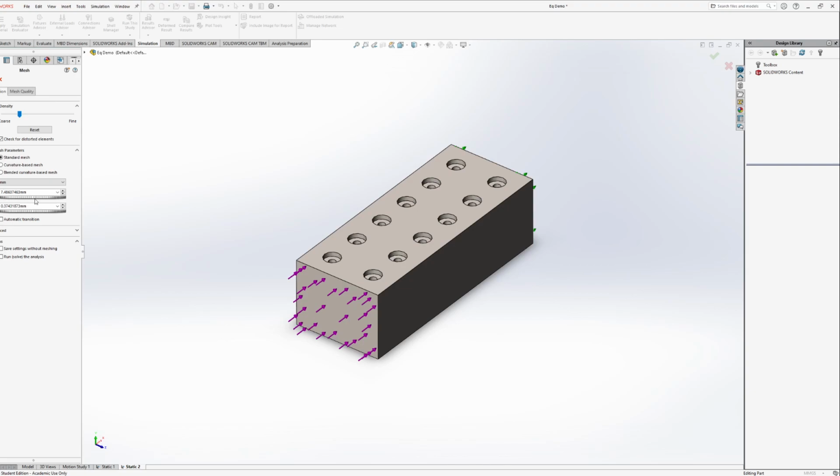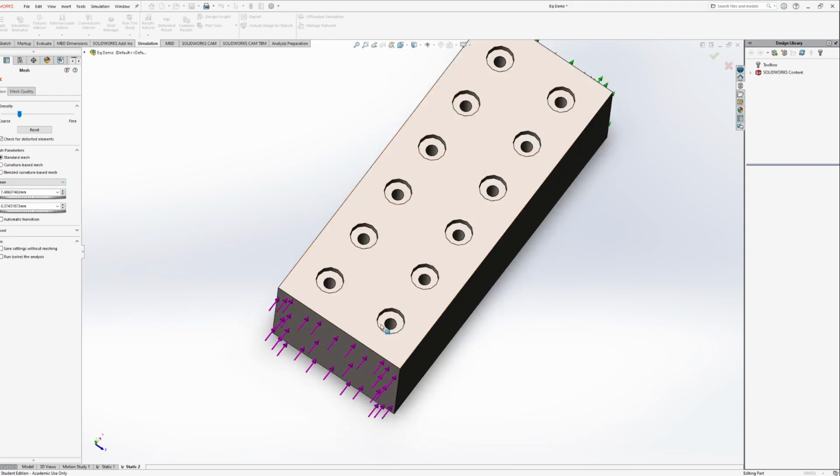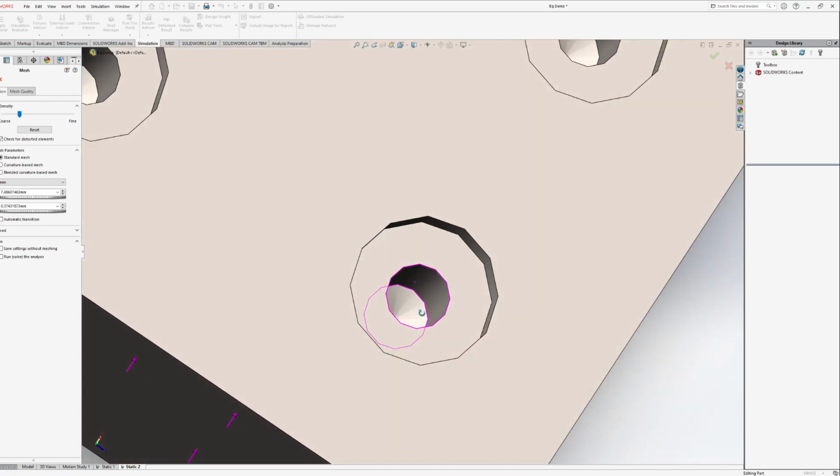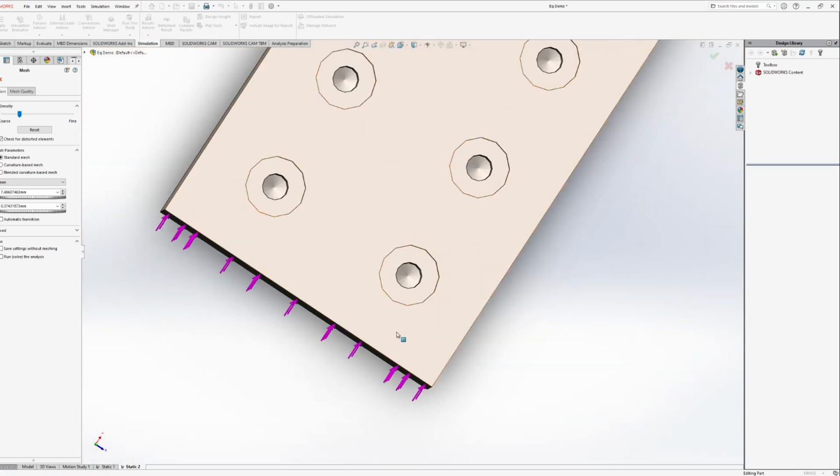So it's basically saying that I have a general mesh element size of around 7.5 millimeters plus or minus 0.3 millimeters to go along with it, because we're not always going to be able to create a mesh where you can fit an exact number of those elements of a given size into this geometry, especially when you're dealing with curved surfaces and things that are very odd shapes.